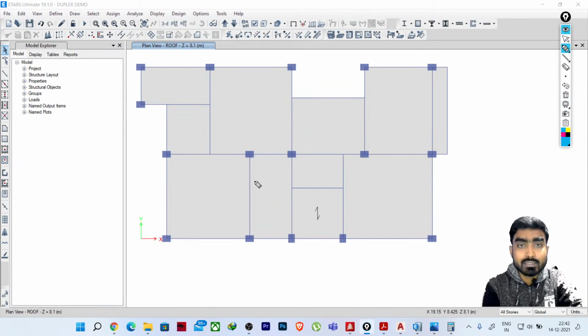But in this direction, we have a smaller span here, we have a higher, longer span here. So in that case, when you will see that this moment will not be balanced by the load from two sides. Okay, so we will be having higher moments in this orientation. So that's why I have changed the column orientation. Okay, for these columns also, if you see for this end columns, now in that case you can orient accordingly because all the beams are same. Now for this intermediate column, it is a matter of concern because this column and this span are almost same.